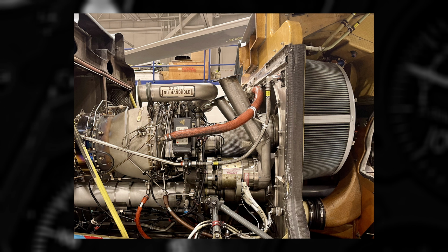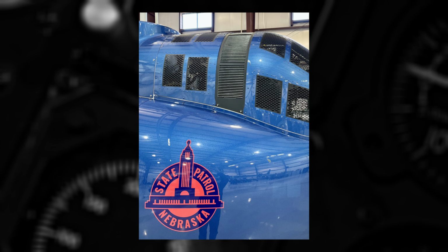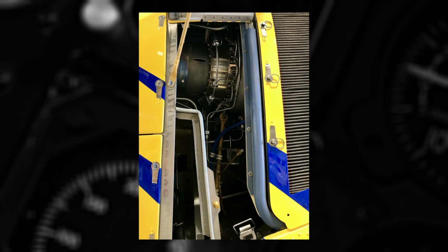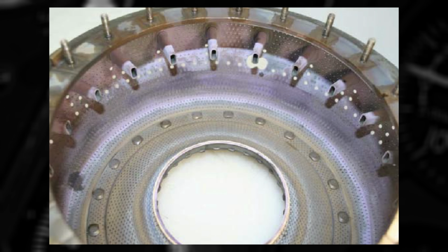Aircraft equipped with barrier filters are not exempt from air path cleanings for several reasons. The filter installation does not stop all of the particles in the environment from reaching the internal passages of the engine. Oil pulled from the filter helps atmospheric particles adhere within the engine. This is another reason to thoroughly clean, dry, and oil your inlet filter properly. Too much or too little oil are equally detrimental.